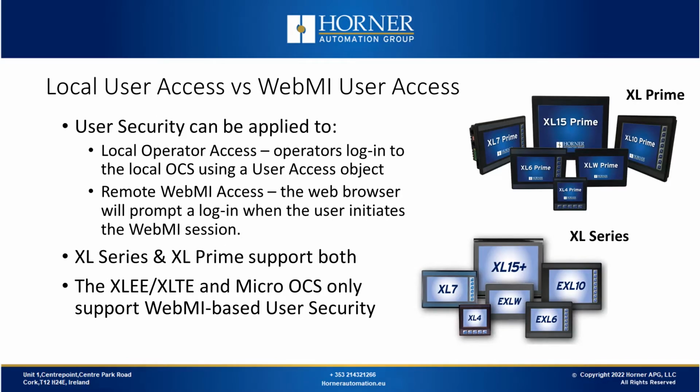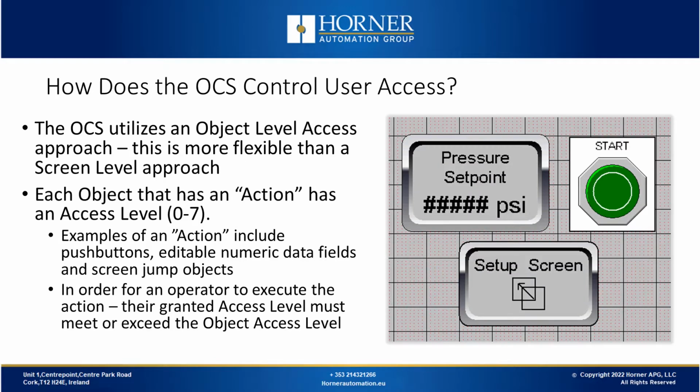User security can be applied in two different ways. First of all, you can think about user security in relation to the local operator interface, where the operator logs into the local OCS using a user access object. You can also talk about user security in relation to WebMI, which allows you to remotely monitor and potentially control your OCS from a web browser. The XL series and XL Prime can support user security for both local operator access from the touchscreen as well as remote WebMI access, while our products like the XLE, XLT and the Micro OCS families only support WebMI based user security.